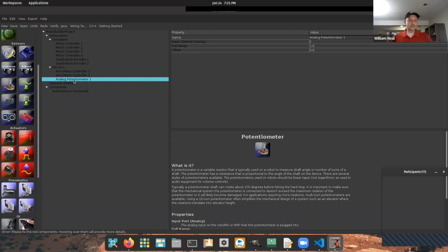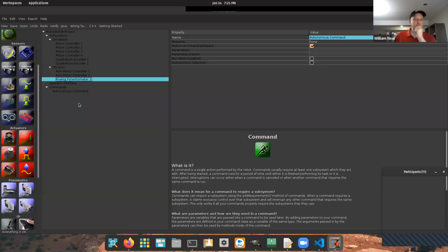So you would just design some kind of way that when the arm moves up or down, this potentiometer turns, much like an encoder, and you can measure the resistance on it with some circuitry and some study of how the resistance changes between the pins as you turn this dial or knob. Okay, this is all just for example, and on your robot, you may have a different configuration, though this one gives a reasonable example.